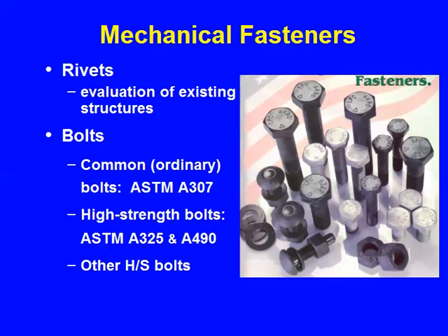Let's start with rivets, though. Why would we need to talk about rivets? And we're just going to say more or less the next few minutes, and that's all. It's particularly the evaluation of existing structures. When you think about it, there are tens of thousands of railway bridges out there, for example, and railways can't simply abandon them and say we'll replace them all because they're 110 years old. So you as the engineer have to be able to evaluate existing structures that are riveted, and usually that means evaluation for fatigue, not always.